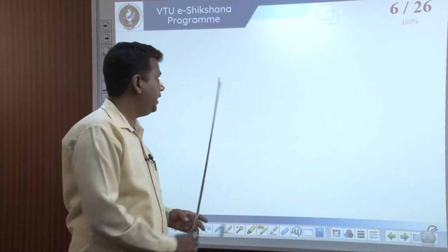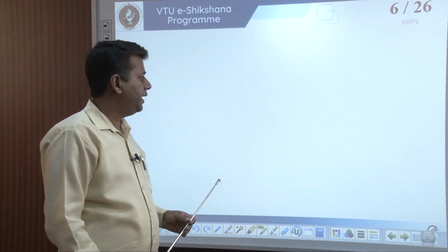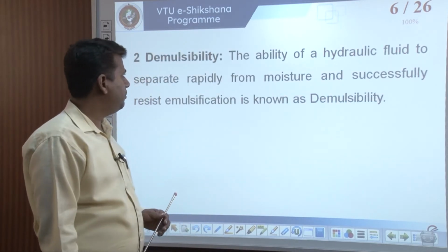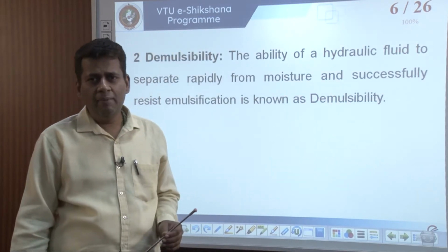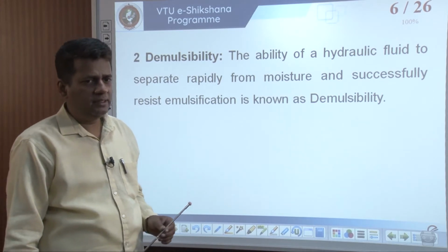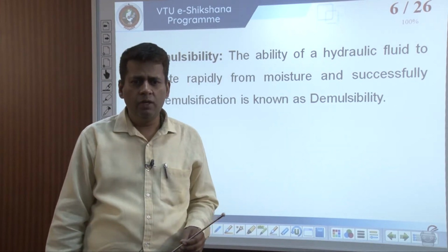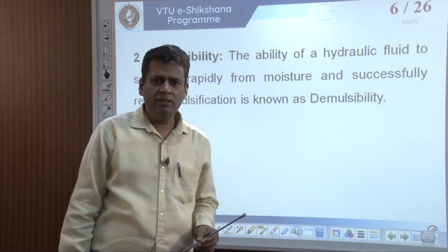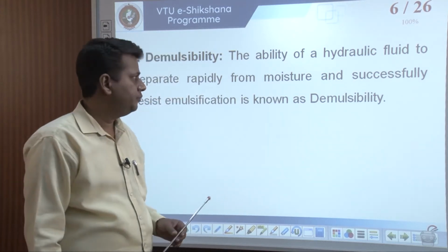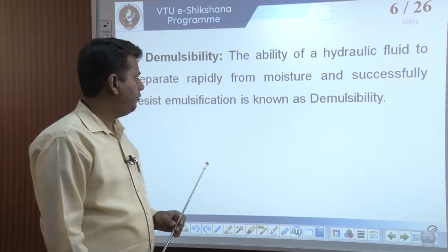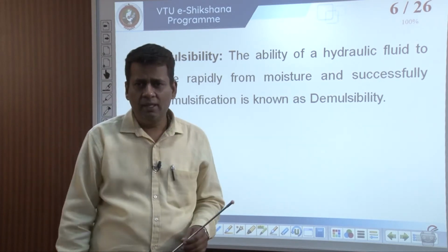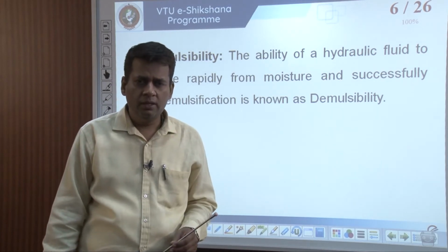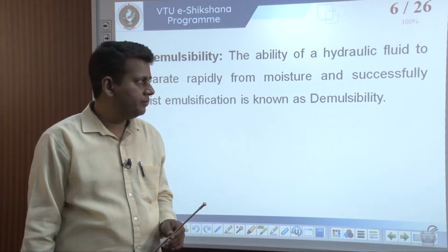The next property which is very important is demulsibility. Emulsibility is nothing but dispersion of the hydraulic fluid, so demulsibility is the reverse of that. The ability of the hydraulic fluid to separate rapidly when it comes in contact with moisture is called demulsibility.